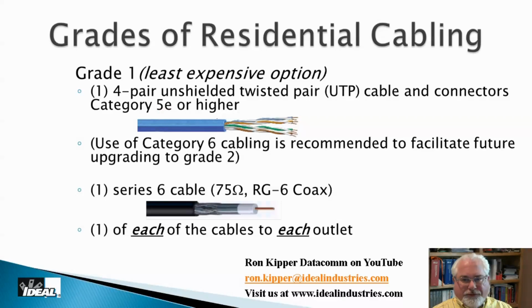Now, as far as the category cable is concerned, about which ones you want to install, the recommendation today is Cat 5e at a minimum. We recommend Cat 6. Years ago, this used to say Cat 3 recommend 5e, and somewhere down the road, is this going to say Cat 6 recommend Cat 6a? I can almost bet you it will, but when that happens, I can't really tell you. But so minimum Cat 5e and at least one Category 6 cable, or one of the two, I should say.